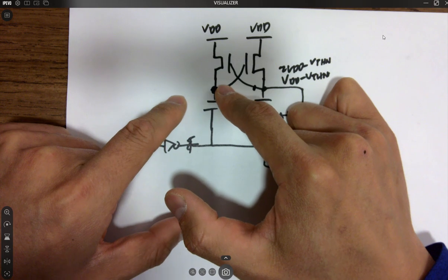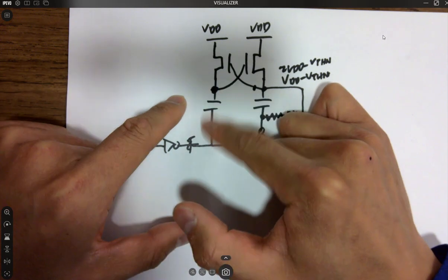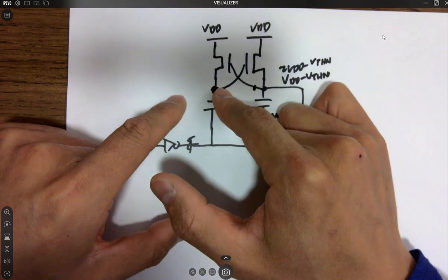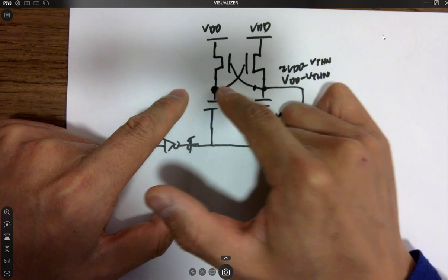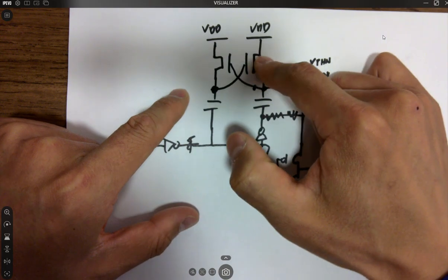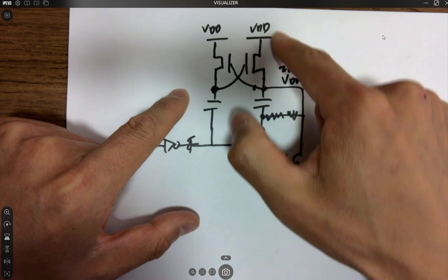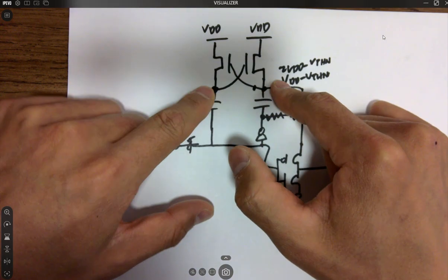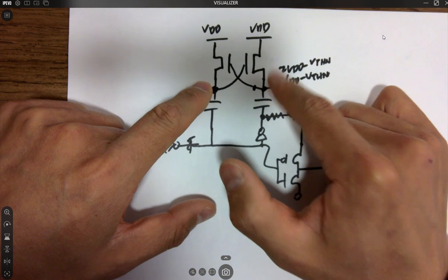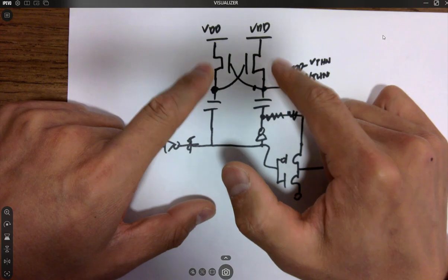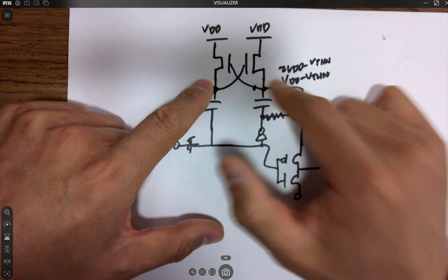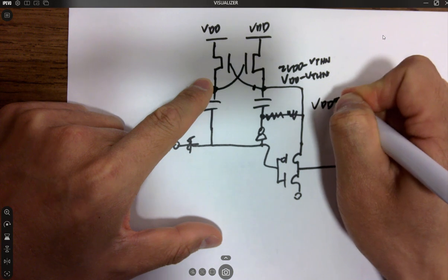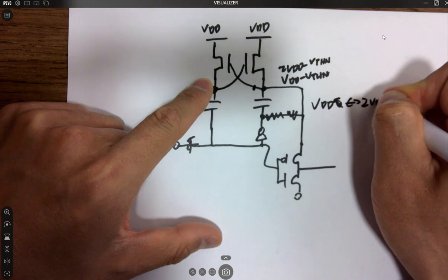Okay? And then when it pushes again, it will directly push to that 1 VDD, so it becomes 2 VDD. If this becomes 2 VDD whenever this is pushing, this is widely open, so when it pulls, it will be able to pass the entire VDD over here, and next time it pushes, it becomes 2 VDD. So both points are swinging between VDD and 2 VDD after the first cycle, eventually. Keep that in mind. So it's VDD and 2 VDD over here.